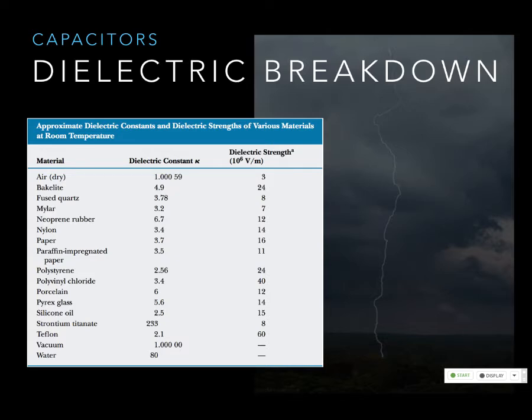So the dielectric strength is the maximum electric field that you can have between two objects before you have dielectric breakdown. Okay? In terms of our electric shock example, if we have a static shock, that's the electric field of about 3 electrons on your finger versus that. As you get closer, what happens to the electric field? It gets stronger. So when you reach this maximum electric field, that's where you get dielectric breakdown. At a particular distance, you'll get dielectric breakdown for any particular electric field, but the electric field is the limiting factor. That's also how lightning happens.